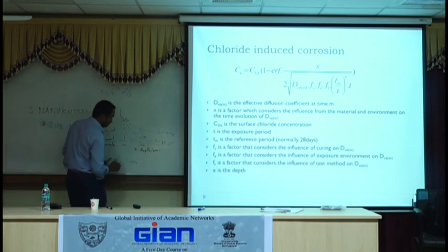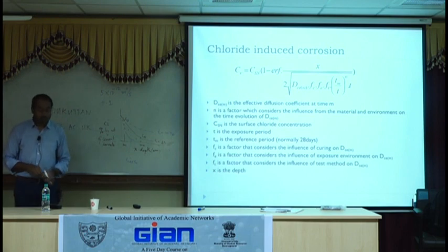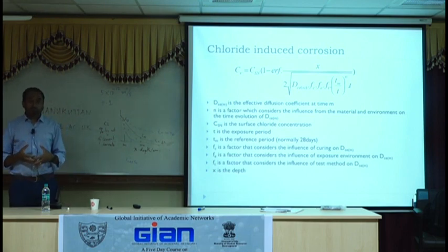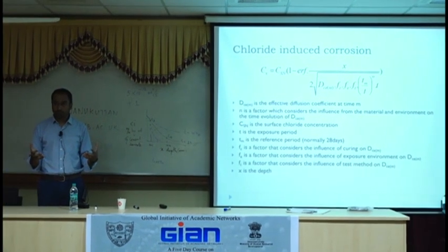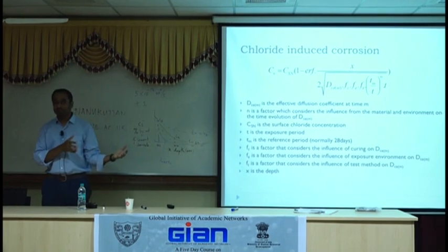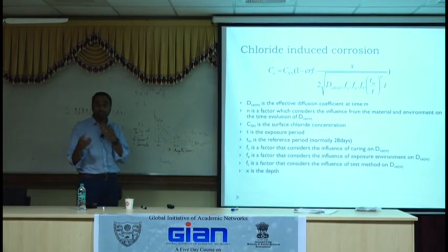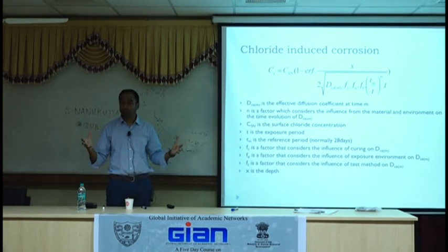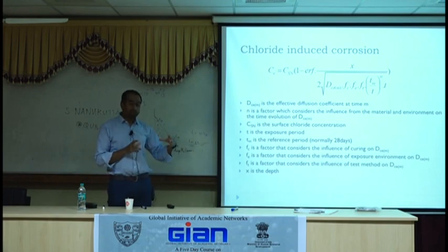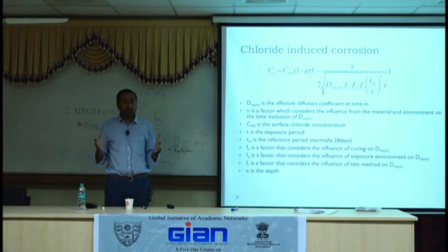True. Okay. Chloride concentration in a concrete will always increase with time. Okay. Given there's no chlorides going out of the concrete. That can only happen if your concrete already had a lot of chlorides. Okay. So if you make a concrete with no chlorides in it, the external chloride concentration, because of the larger concentration on the surface, will try to go into the concrete.